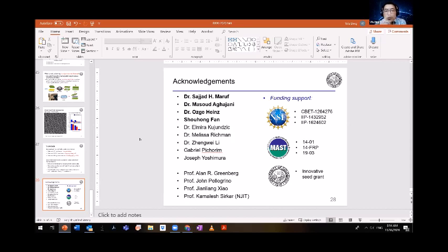There is continuous roll-to-roll nanoimprinting, but so far the focus was not on patterning membranes. Roll-to-roll nanoimprinting in most cases uses UV cross-linking. So you're casting a solution and you contact the pattern in a roll-to-roll fashion and introduce UV for cross-linking, rather than using pressurization and heating like we do. So definitely there are capabilities for scaling this up being developed, but I would say roll-to-roll high pressure imprinting is still not there yet. Okay, great.